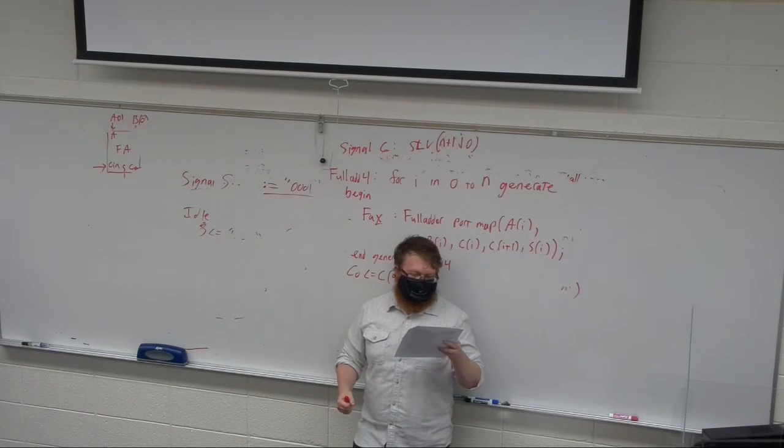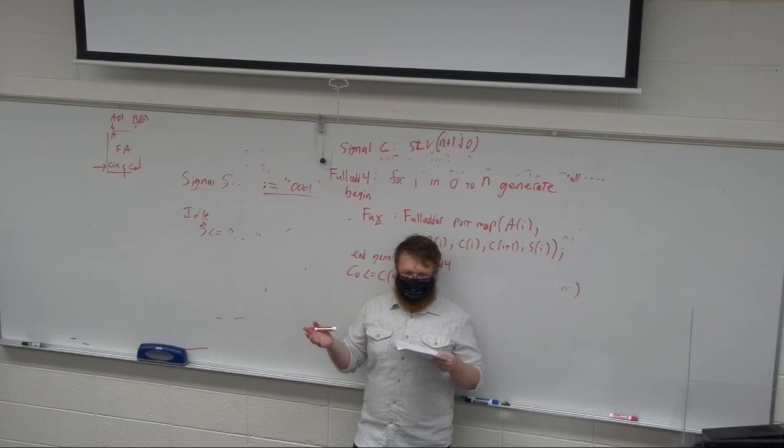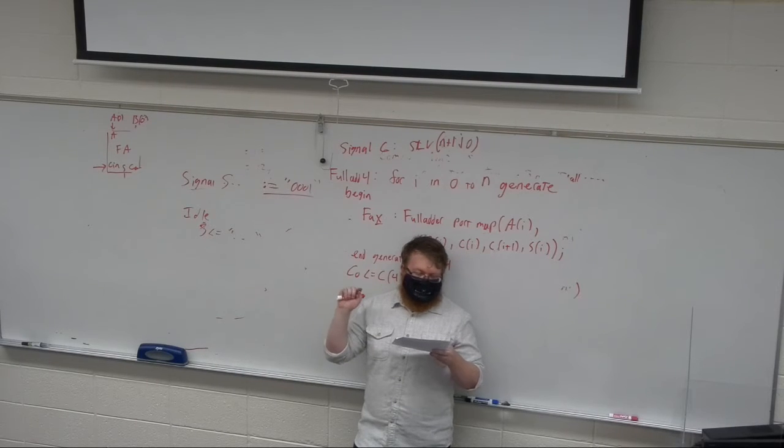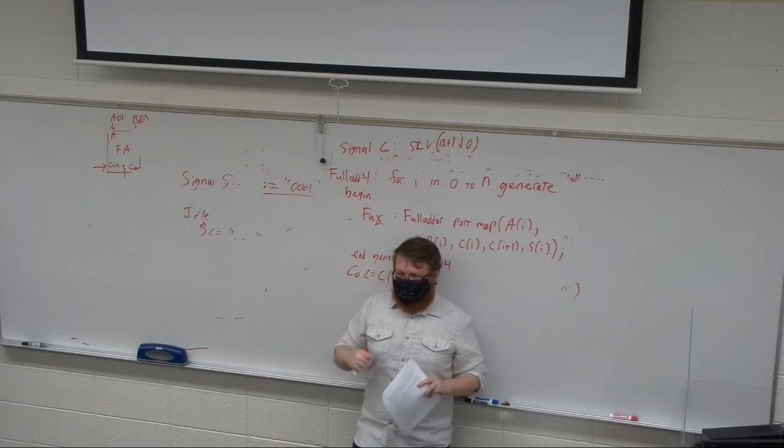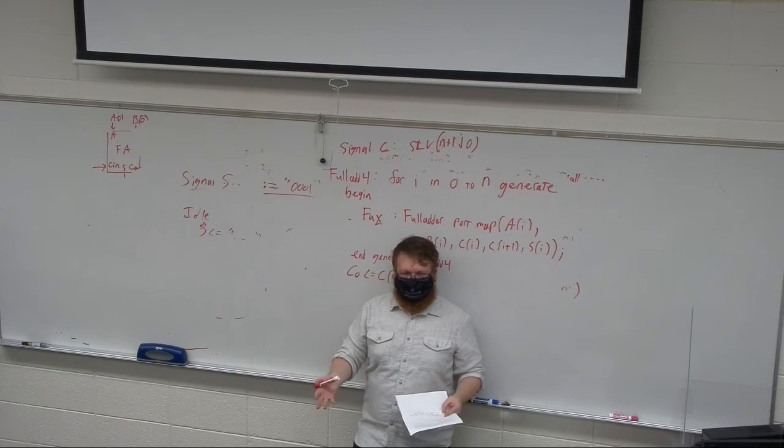But the errors in the test bench: on line 24 was missing a 0, so it just had the wrong number of zeros in the initialization. I misnamed busy in the port, so BSY instead of BUSY. And then this one was the most missed one, the status lights, right? I said you need to correct the issues in the test bench, including those that prevent it from running, and issues causing X or U outputs. So as long as you did something with the status lights, I was okay with it.